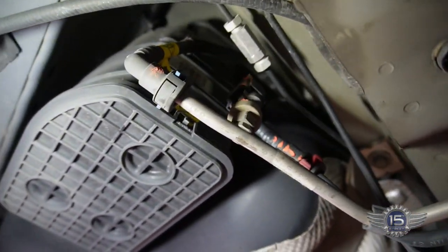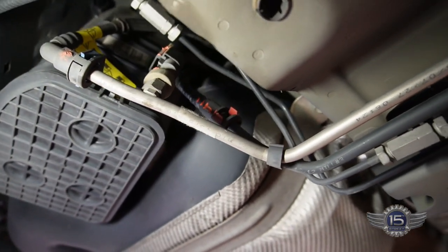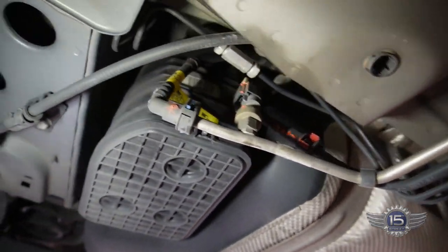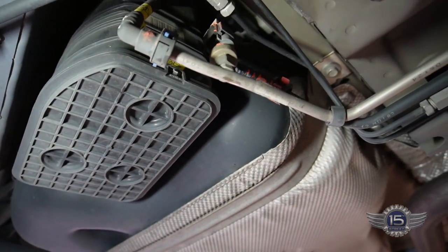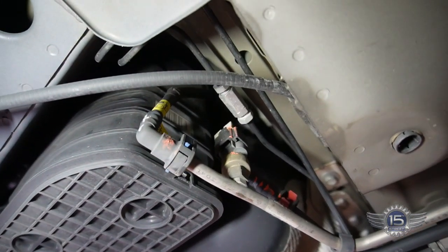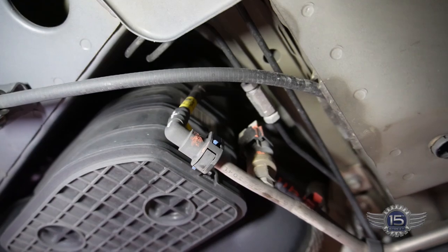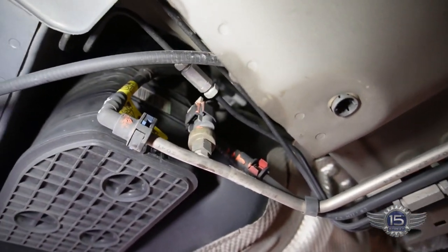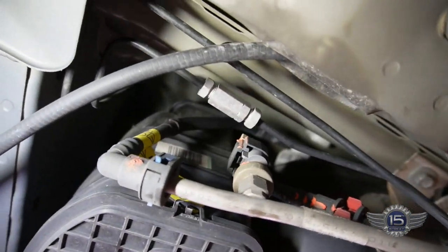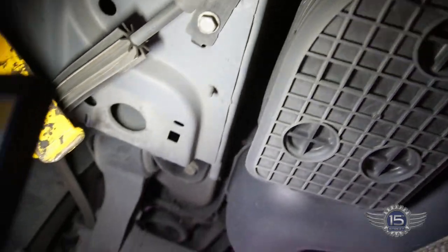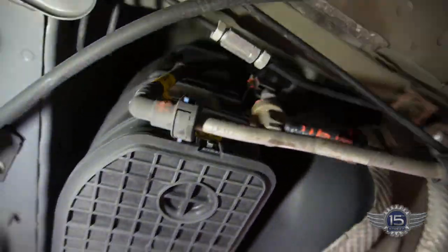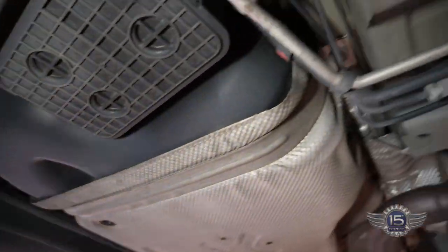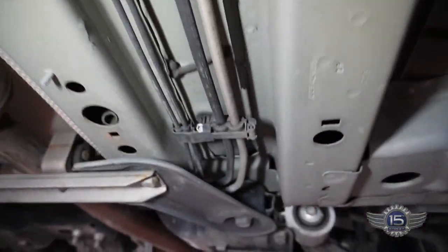So what we need to do is hook everything back up and run this thing with the evap closed and see if that takes care of our problem too. This thing might just be over purging. It might be worthwhile just putting a purge valve on it to see what it does. They're so common, but there's no leak on it, so it's not a purge system leak.